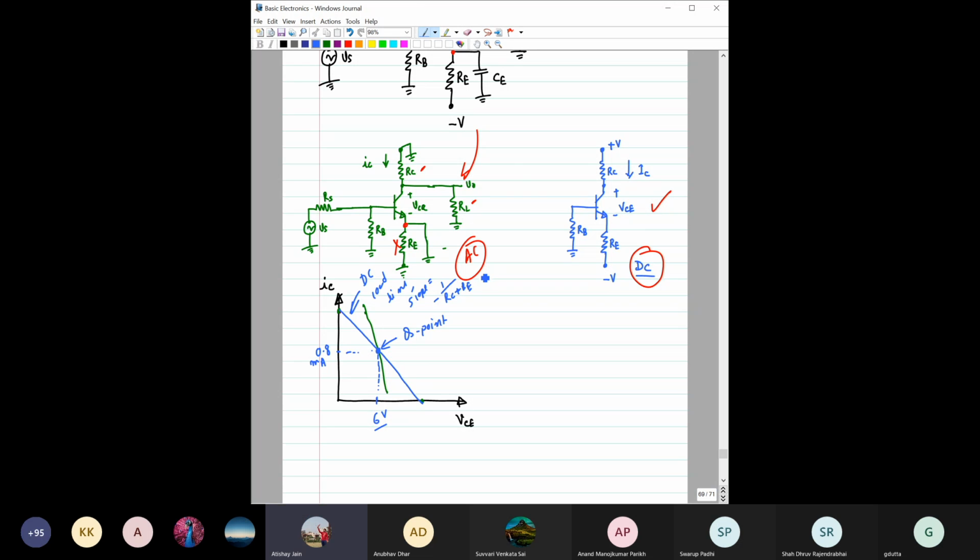Will it be small IC or capital IC? You are right. Okay. So now if you look into this AC part, this is the Q point, right? If you want to also now draw the AC load line, this would be like the origin, right? And now we have to draw a line. What would be the slope of that AC load line?